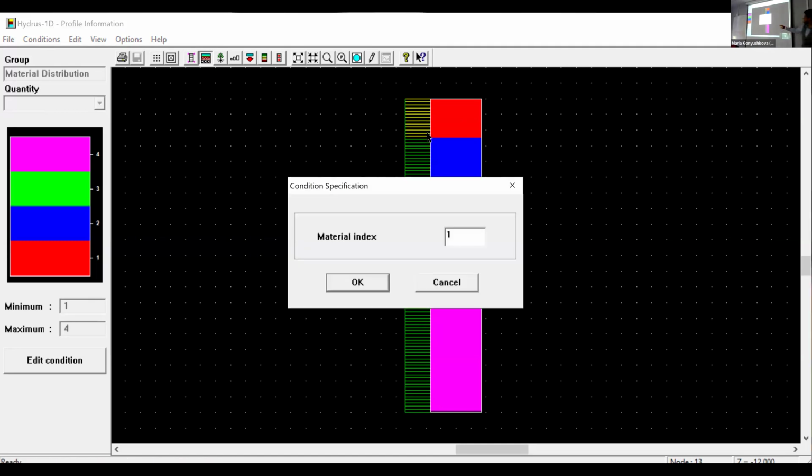And here you can specify the code of the layer number. If you have, for example, 10 layers and layers 1, 6, and 7 were more or less the same, you have to say for 1, 6, and 7 at the specified depth, code 1, because it uses the composition of that row we put in the composition solution.